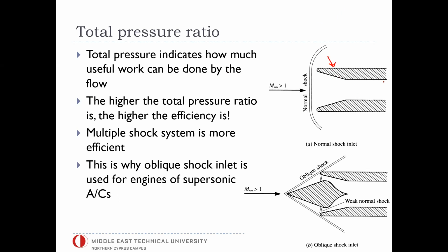So somewhere over here you could have your engine buried inside the aircraft, which is expecting a subsonic inflow condition, and not only subsonic, but a mid-range or low subsonic condition, 0.3 to 0.5 Mach number. You could achieve this only through a normal shock wave, as it's shown here. Okay, you are flying supersonically.